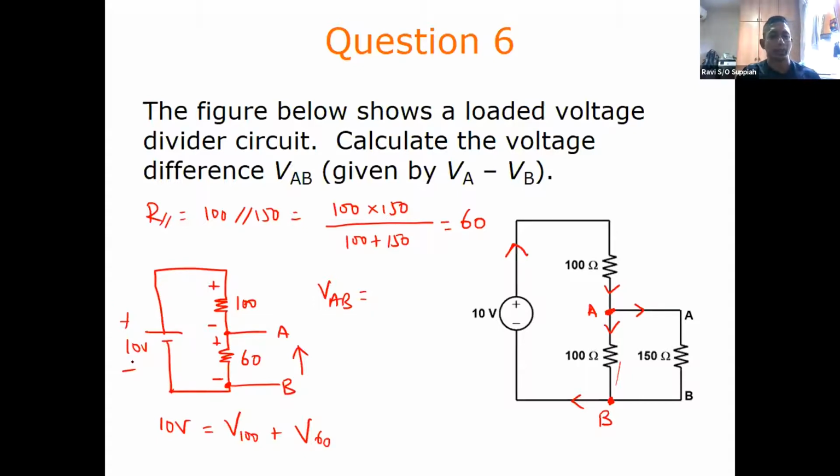All right, so for this source, the positive is on top, negative below, so current is flowing in this direction. In this case, this is the opposite. So if I were to draw a loop like this, you can say that this is the source and this is the drop, this is the drop. So in terms of Kirchhoff's voltage law, this is what you can get.